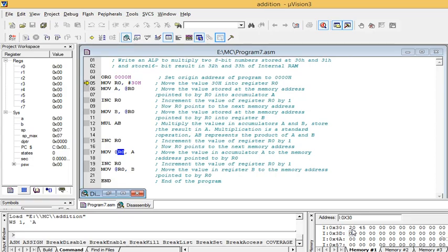So you can just go through the calculator in hexadecimal. 20 into 45 will be equal to 08A0. We shall check that. Go to the step value. The immediate address has been moved. Here I have stored 20. The same value has been moved to A here. Therefore, we are incrementing R0, that becomes 31. Once again, the 45 value stored at 31H has been moved to B.